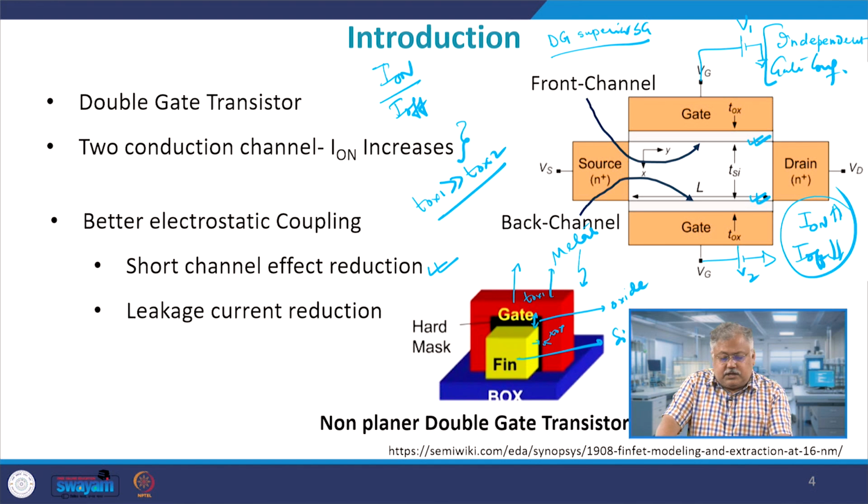This is the structure of a FinFET, we will study it later on, but this structure is very simple. This is a gate, I have a source on this side and I have a drain on the back side of your screen. So, the current flows in this manner inside the screen, and from drain to source the conventional current will flow, and who will create the channel? The gate will create the channel. The red colored material which is placed here will create the channel.